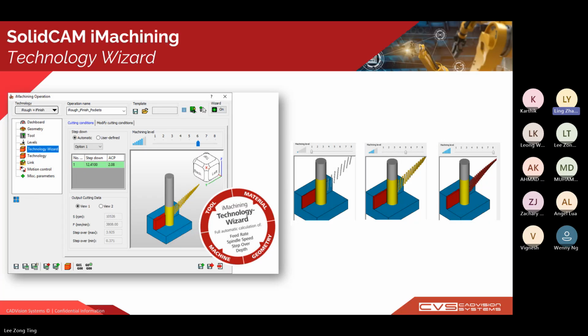It's built for real-world conditions. With the eye machining level slider, which you can see from the left picture at the top right corner, there is a machining level from 1 to 8. You can choose from the 8 preset levels to match the stability of your setups. Level 1 basically gives you the most conservative settings.